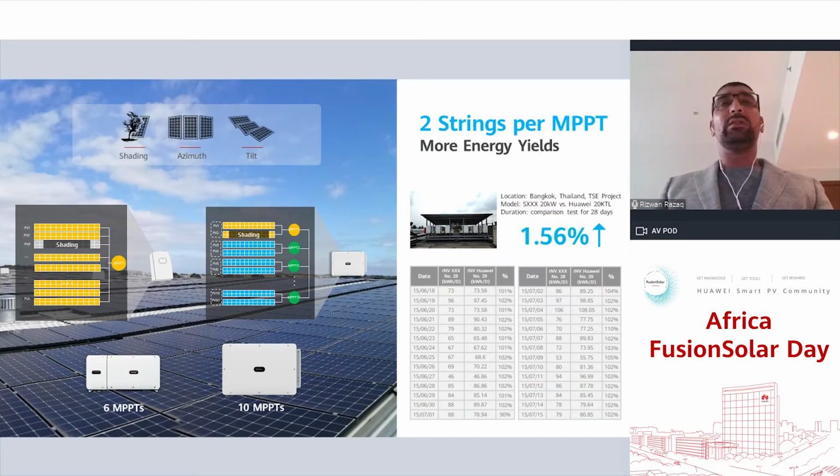With all the Huawei inverters being supplied to the market for the CNI and utility scale applications, Huawei has adopted a 2 strings per MPPT design. Now, as we can see from the slide here, where there is a product with a single MPPT, that inverter would overall be impacted in its performance compared to a product which has multiple MPPTs. And if one particular MPPT was to be impacted by a shade, it will only impact that particular string or MPPT rather than the overall inverter itself.